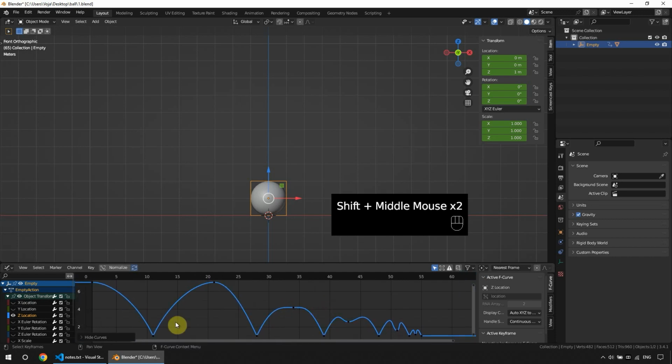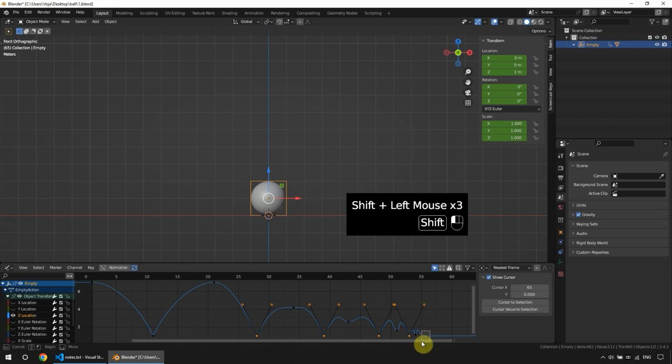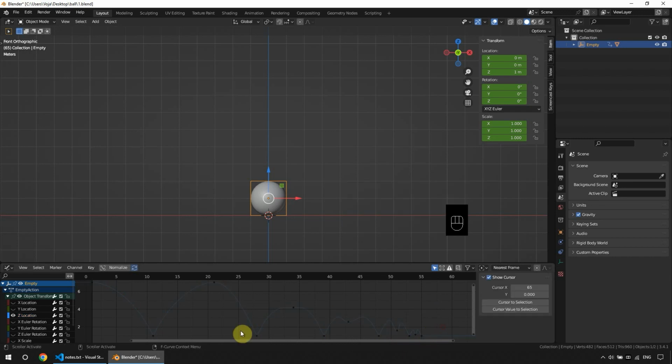And this is because we changed this first keyframe to vector, if you remember, and now all of these are vector, which isn't what we want. It kind of is, but not right now. So what I'll do is I'll select these bottom ones. So every second one, make sure to select. Let me just do it again because it's a bit hard to see.